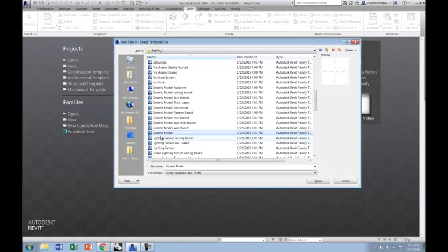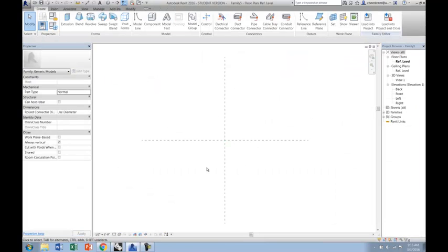It's not a conceptual mass type model. It's actually a generic Revit model, a traditional family type. We're going to try to keep all of this in that. This model is really set up for using the traditional curtain panel system in Revit. All right, so opening up that generic model, here are those reference planes I was describing. In the reference levels here, we're looking at this in plan. We're going to need to move back and forth between elevations, or between elevation and plan.